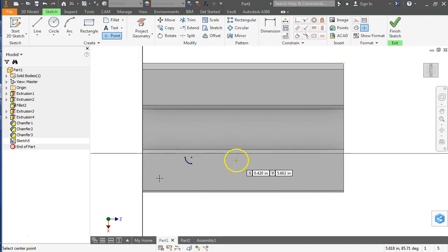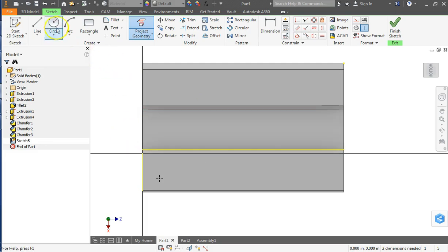Now, this sketch that I'm on, this surface, there's actually no geometry except for the point that I created. Any of the edges or things in the background, they are not on my sketch. And when I go to use a tool, like extrude or hole or revolve, I need to select geometry. That's all part of the sketch that I'm creating right now. So I'm going to project geometry, just because I know how to use the rectangular pattern tool a little bit. And I'm going to bring on a line that in this case for my orientation is vertical and one that's horizontal. And it doesn't matter at all what line, I just need to project a line. Okay, I could even use the line tool and just create a couple lines, but now I have those to reference.